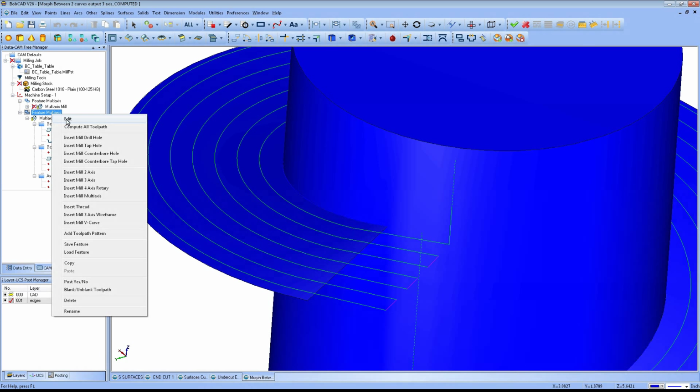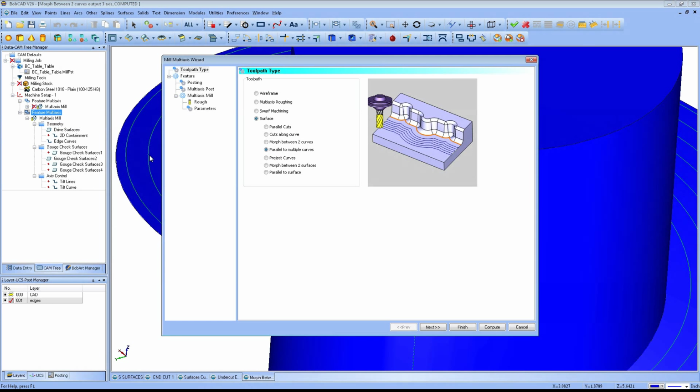That's the one thing about these toolpaths that you want to understand, and even with any of the 3-axis and 2-axis toolpaths nowadays, is once you generate it, take a look at your toolpath on the screen. If it's not what you want, go back into it, make an adjustment, recalculate it. Look at the toolpath generated on the part, look at the simulation, start tweaking it in. It's a lot easier to get the basic toolpath calculated first and then tweak it in from there than to just try and go right to the finished product the first time, and guess on half your settings probably as you go through it.